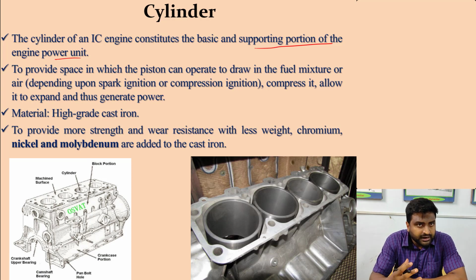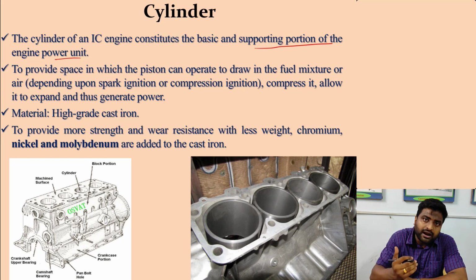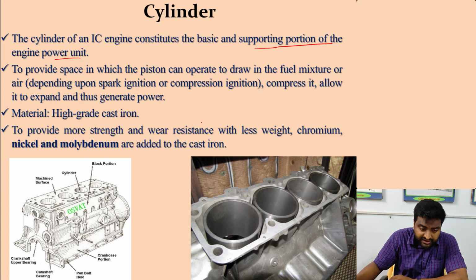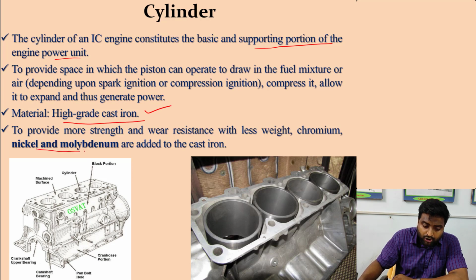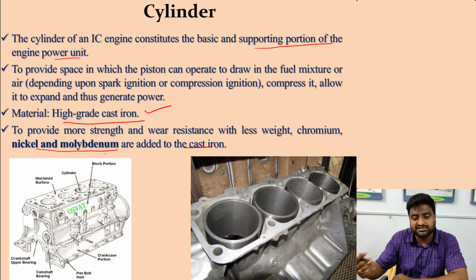Or you can say it is the space in which the piston reciprocates up and down and the power is generated, or the heat energy is converted into mechanical energy within this cylinder only, right? So the high temperature is generated, that's why the material is mainly high grade cast iron, or nickel and molybdenum are added to the cast iron so that more strength and wear resistance can be given.